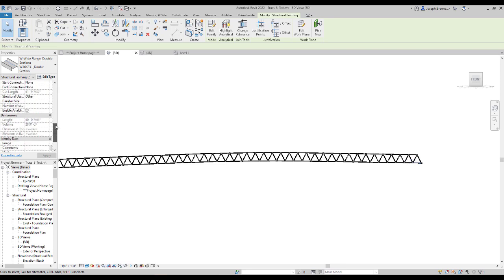Okay. So I'm just going to roll down here again. There are many different options here, but we have the length of every single member as well as the volume of every single member, and that can be turned into a weight. It can be scheduled for every single bar here. These are all Revit elements that can be scheduled now for quantities and exported to Excel sheets and what have you. So that may seem obvious, but it's extremely helpful, especially when we want a different truss configuration: we change our script, we update that, and our schedules are automatically updated as well.